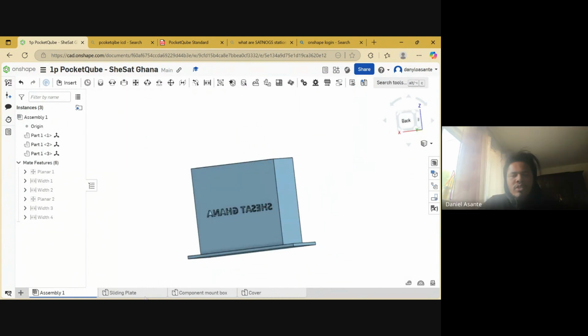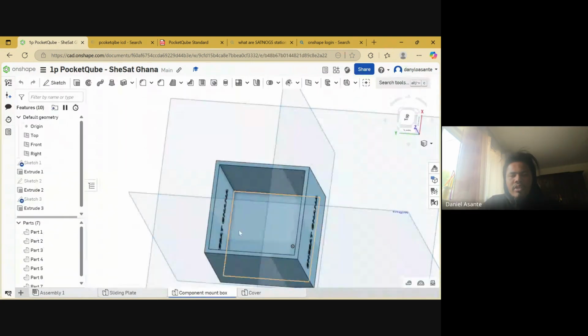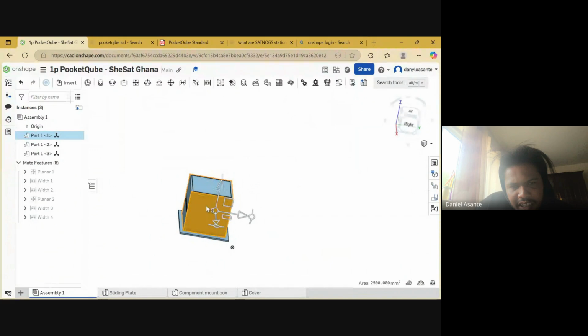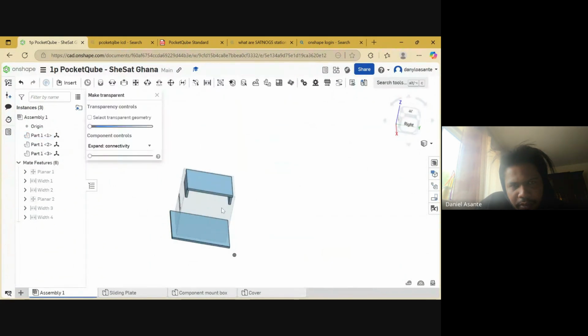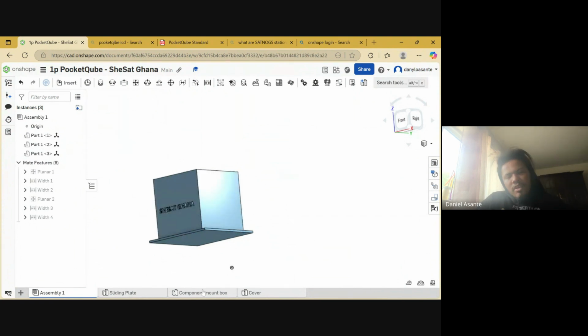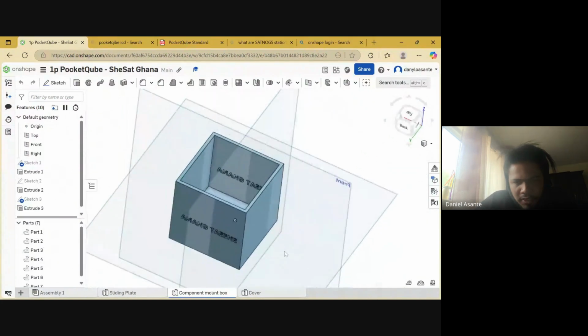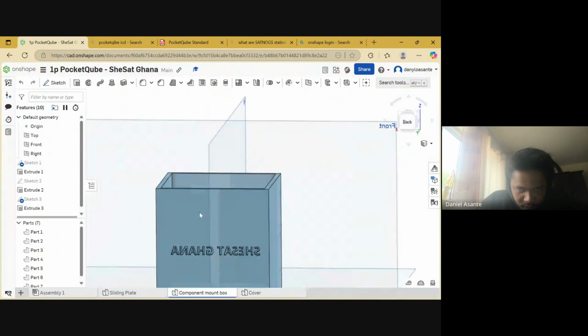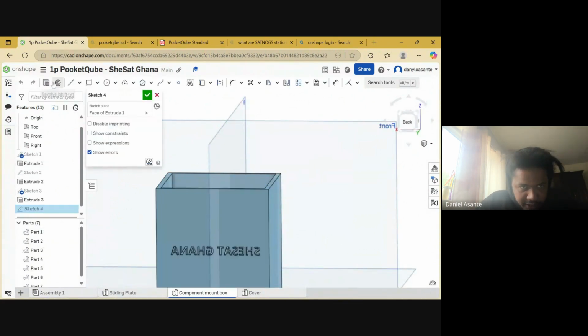So I'll come to the components box now. Let me see, where is the cover, the line for it, make transparent. So it's on the top plate. Okay. So I'll come to the top plate and I'll make two holes. Two sketch. So again, you can click on circle to make the hole.